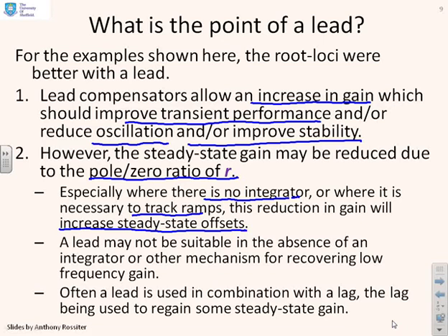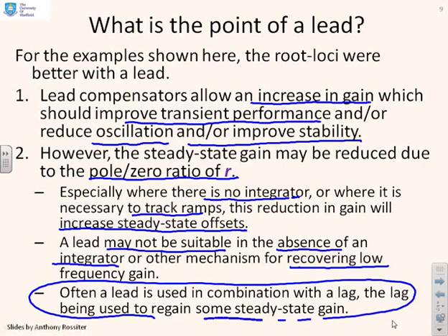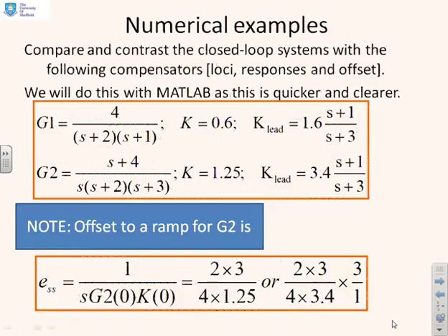Therefore, a lead may not be suitable in the absence of an integrator or some other mechanism for recovering low frequency gain, and therefore you'll find that often a lead is used in combination with a lag or some other means of recovering steady state gain.